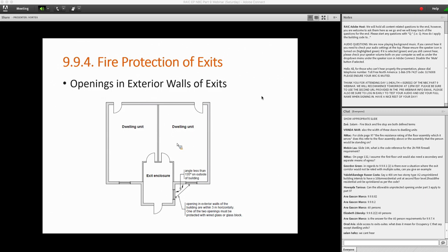The lobby referred to in sentence 1 shall conform in all respects to the requirements for exit, which is what I just discussed, except that other rooms are actually permitted to open onto the lobby. However, if you have a service room, a storage room, or rooms of residential or industrial occupancy, they are not permitted to open directly onto the lobby that is being used for exit discharge.